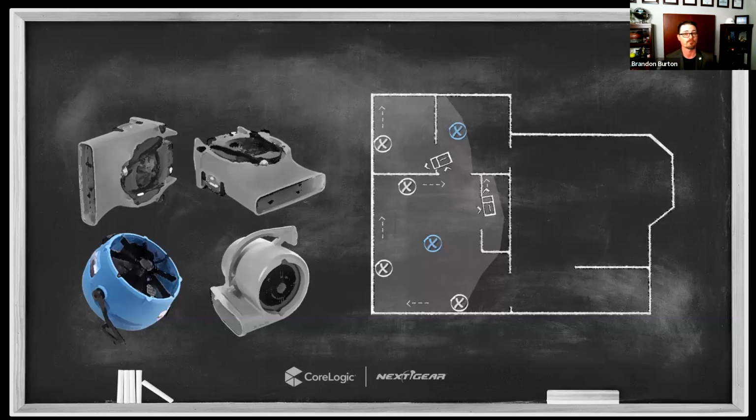This is critical. It is standard of care to ensure that you have air movement across all wet evaporating surfaces. That comes right out of the S500. You must have that in your initial installation. If you do not, then here's what's going to happen, right? All the surfaces that have it, they're going to dry well for the first 24 hours. But the surfaces that don't have it aren't going to dry well for the first 24 hours. In fact, they're going to get wetter, right?